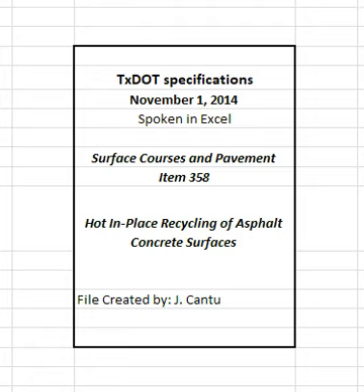The engineer may elect to have the cores transported back to the department's laboratory at the HMA plant via the contractor's haul truck or other designated vehicle. In such cases where the cores will be out of the engineer's possession during transport, the engineer will use department-provided security bags and the roadway core custody protocol located at http://www.txdot.gov/business/specifications.htm to provide a secure means and process that protects the integrity of the cores during transport.